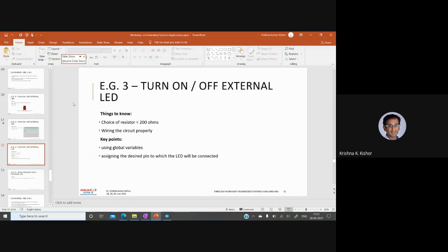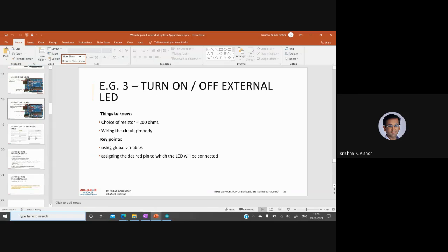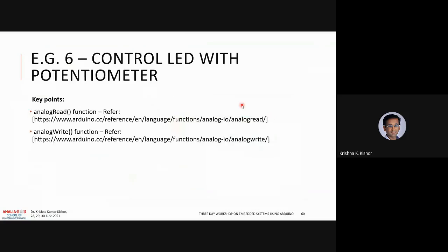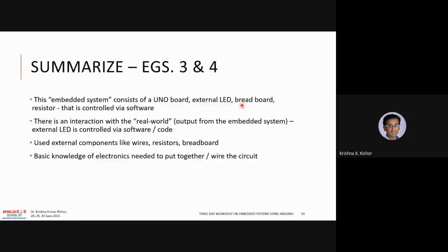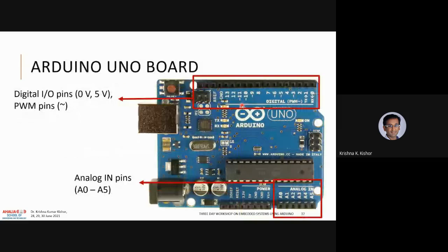Let's go back to the diagram. These are the PWM pins, so see the ones with the tilde sign. I can use only these as an output.